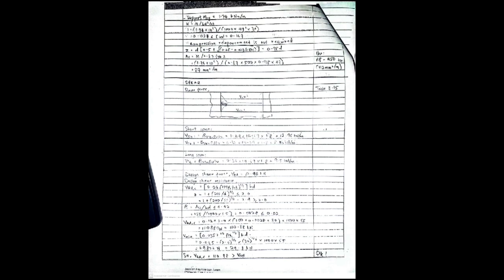As you can see, this is the analysis for this two-way slab design. We got the value of short span and long span for the bending moments. And this is the main reinforcement that have been calculated, and we got the value to use for this two-way slab design. Then, this is the shear force for this two-way slab design. The design shear force, we choose the greatest value, that is 12.69 kilonewton, and after that we got the VRDC equal to 110.88, which is greater than the design shear force value, so it is okay to use.